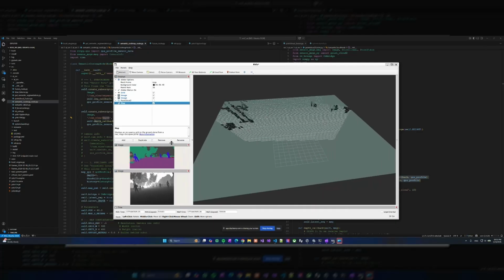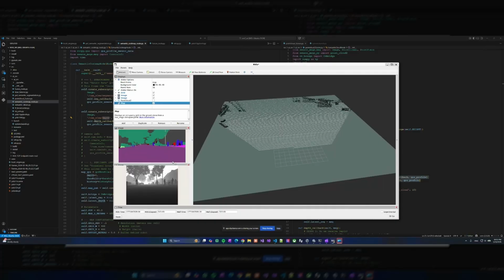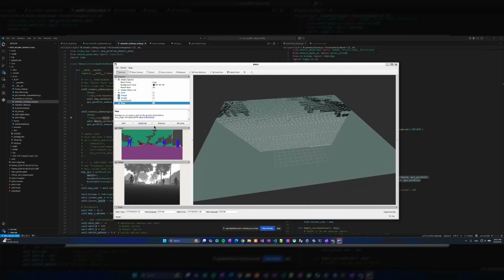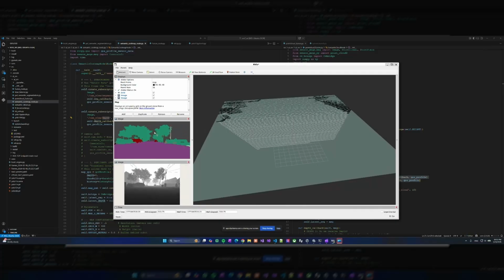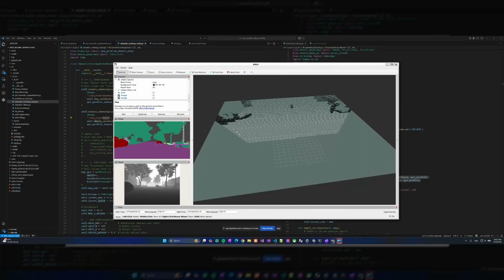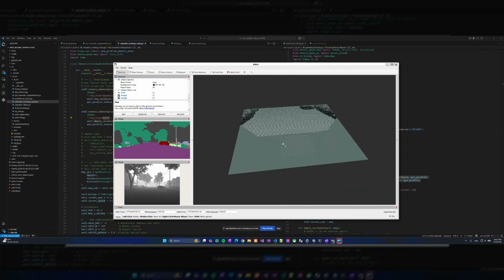All right, if you make it larger, down here you see a depth map in grayscale. On top, the purple represents the road, and these humans and trees all represent the obstacles. Okay, based on the depth value as well as the semantic segmentation, we can project that depth down onto the floor as a 2D image, right?